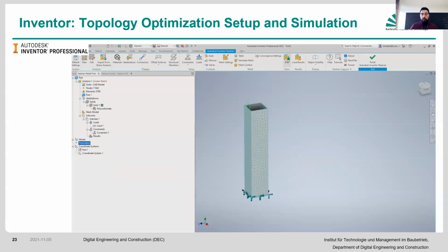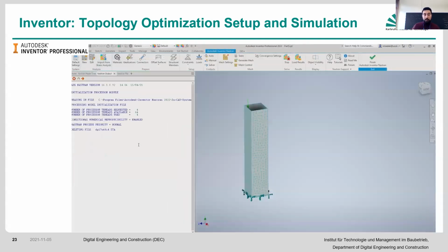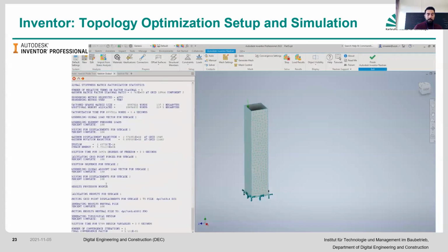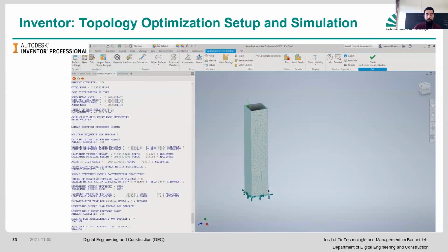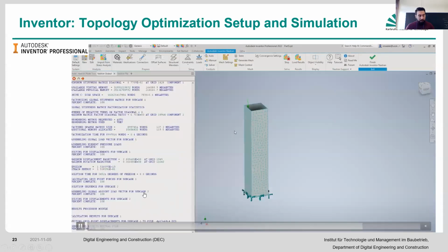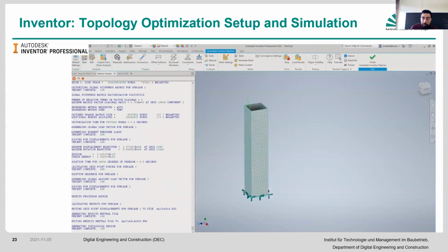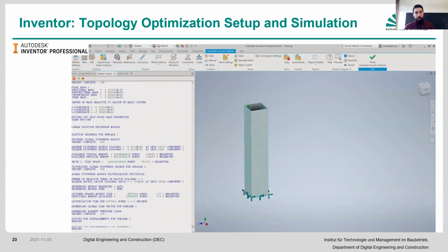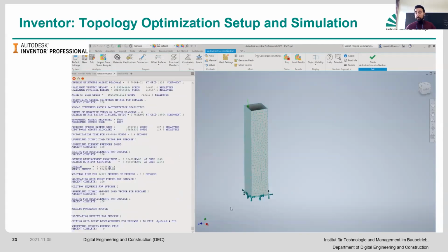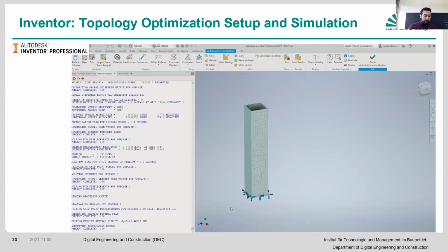So here I'm just going to do a run with respect to regular stress analysis, and then you save your results and then take it from there. However, you're more than able to perform whatever you want to perform here as well. And then at the end, once it does its work with the Nastran solver that it uses, you would then have the ability to see what the stress is, what the strain is, and so on and so forth, the von Mises stress, the displacement, and all of these items there.